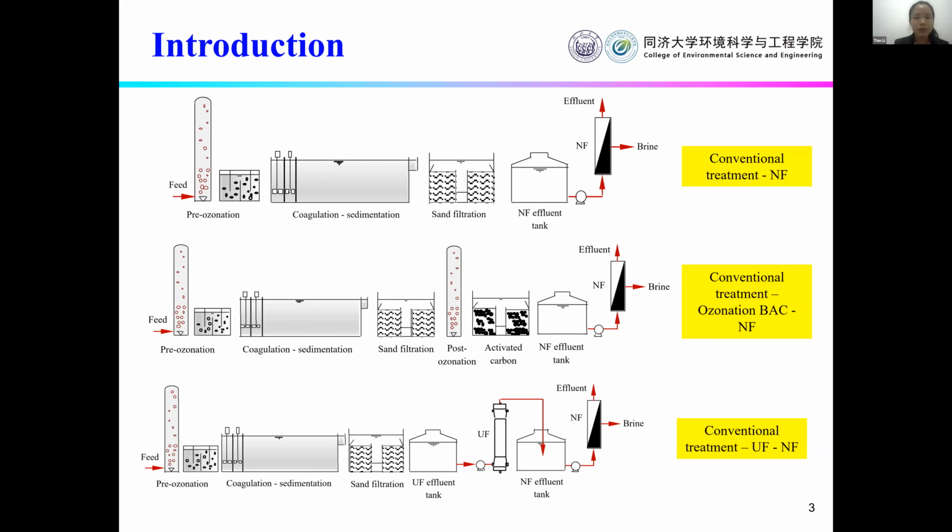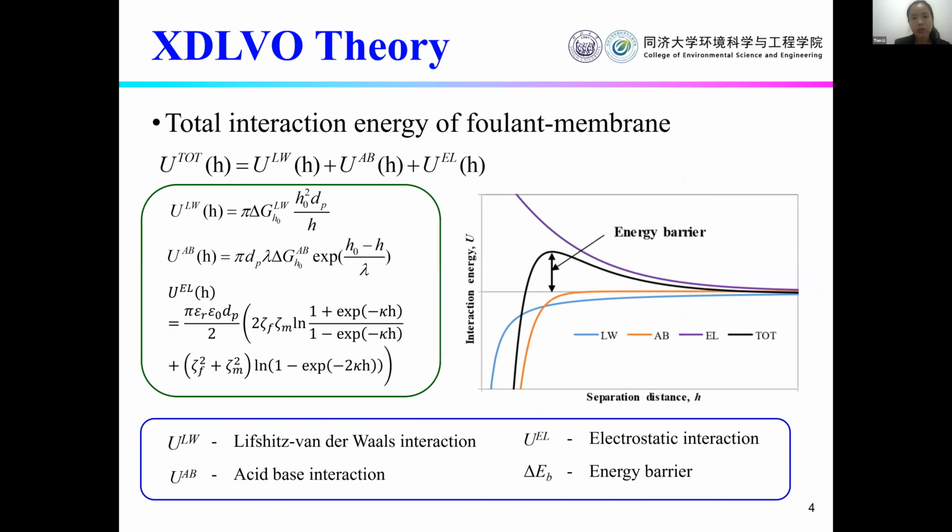In the past few years, nanofiltration membrane fouling has been characterized by the XDLVO theory. The XDLVO theory describes the total interaction energy of three parts: one is the van der Waals interaction, the second is the acid-base interaction, and the third is the electrostatic interaction.